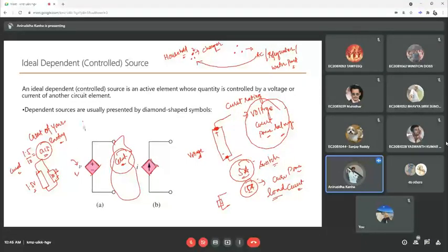Similarly, if I connect a 3 ohm load to your battery, which is again 1.5 volts, then 1.5 divided by 3 is 0.5 amperes. So the voltage is the same, the load changes based upon your requirement, and the current also changes. That is why it's not giving you a constant current, rather it is giving you a constant voltage. So what is the current rating for that particular battery?